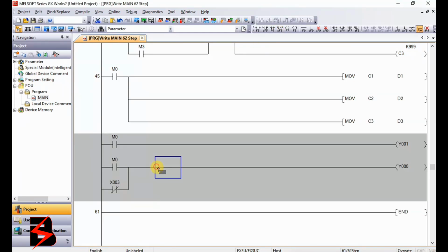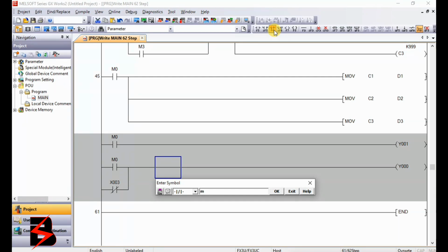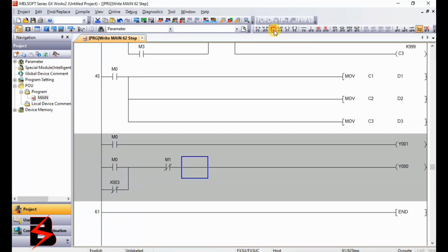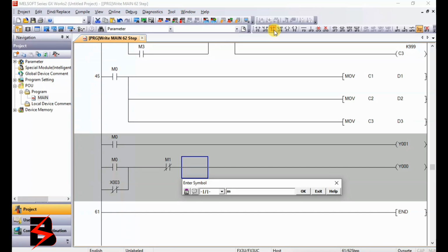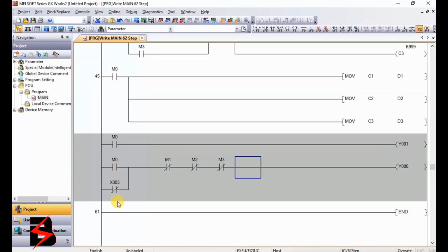That means it's going to be stopped by M1. So when the object is sensed, the conveyor will first have to stop to prevent congestion. You're just going to see when it is simulating. So it's going to be stopped by M1, it is going to be stopped by M2. That means any color that is detected is going to stop the conveyor, and it is also going to be started by this one. Yeah, I think that is it.